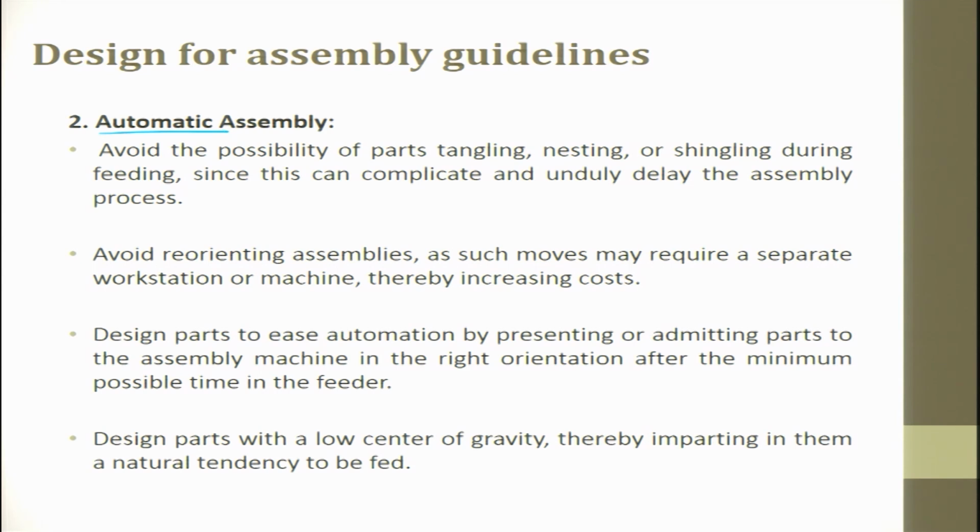So, when you replace the man, the parts which are there in the tray which I was talking to you now have to come through a chute or a conveyor. So, it has to be continuously fed. When you are continuously feeding it, an individual man cannot drop one after the other. So, what we do is we drop the entire parts, maybe few hundreds or few thousands in a hopper, and then from that hopper through the chute the parts keep moving.